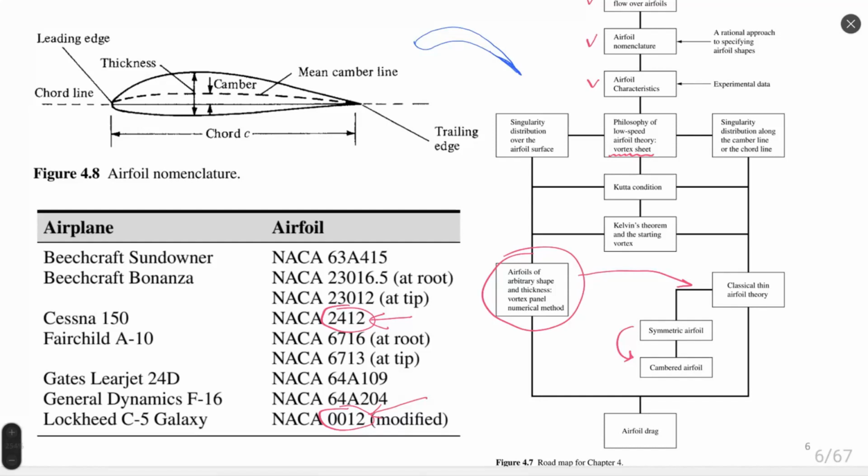In the case of such an airfoil you are asking about, I think we have a significant change of velocity in the X and Y directions because the velocity is rotated. So I'm not sure we can use it, but probably we can up to some limit, but not in all cases can we use thin airfoil theory and its predictions.